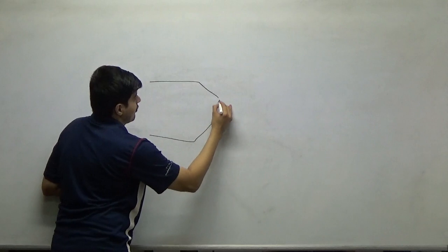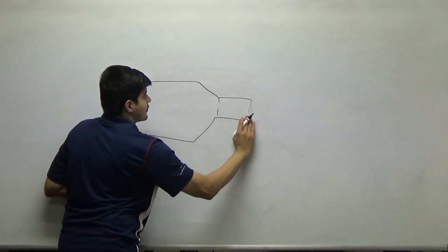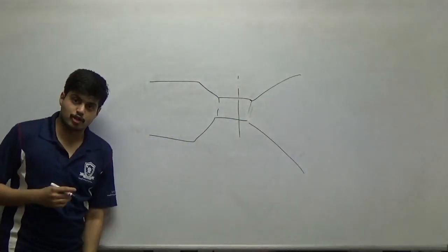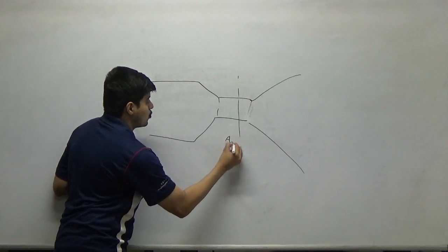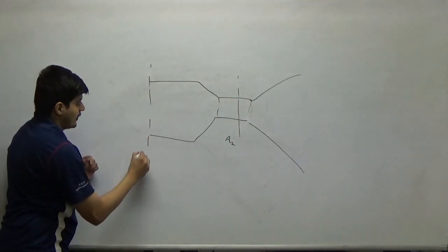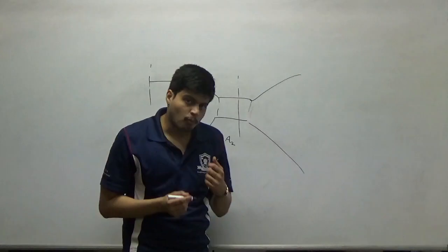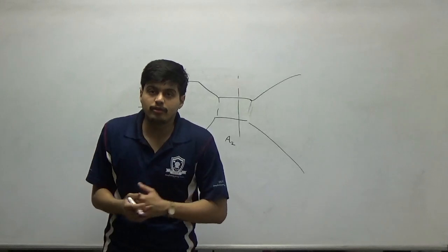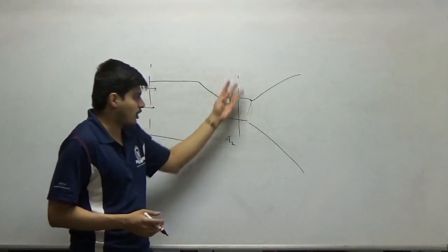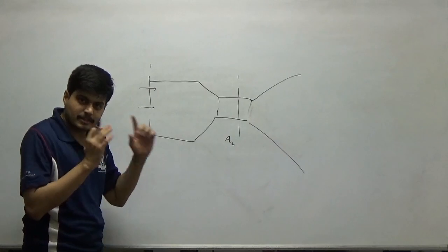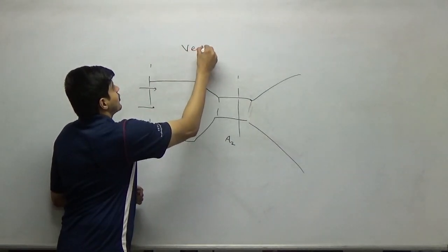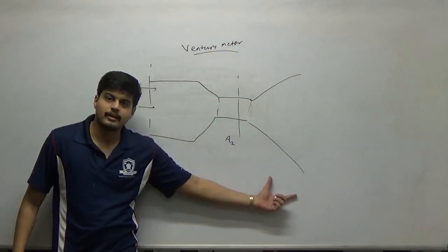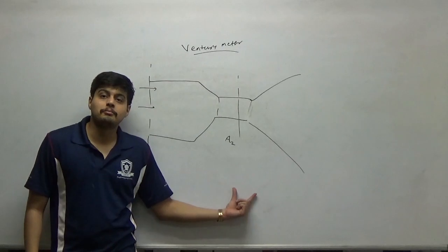So therefore, your venturi is typically denoted something like this. This is that venturi. This is A2, the area. This is the entrance area, A1. Why did we do it? Because the flow upstream may have certain vorticity, may have certain non-uniform characteristics, non-streamlines. We have got rid of them. Once this picture is clear as to what a venturimeter is, we just need to apply a very simple set of equations that we have been learning throughout chapters 1 to 7 and just apply them here.